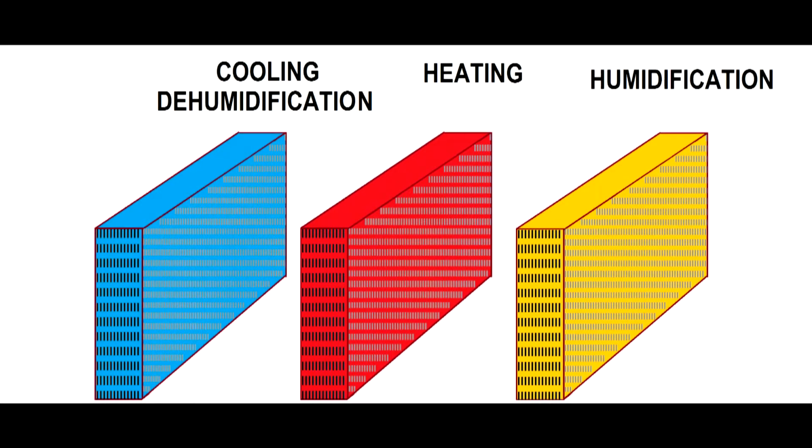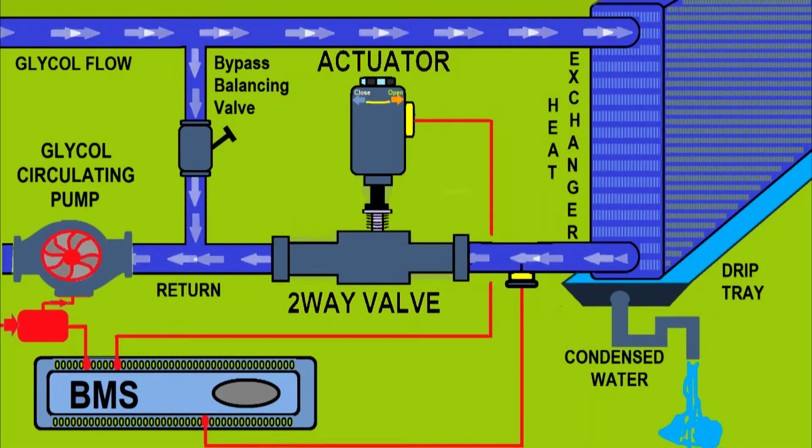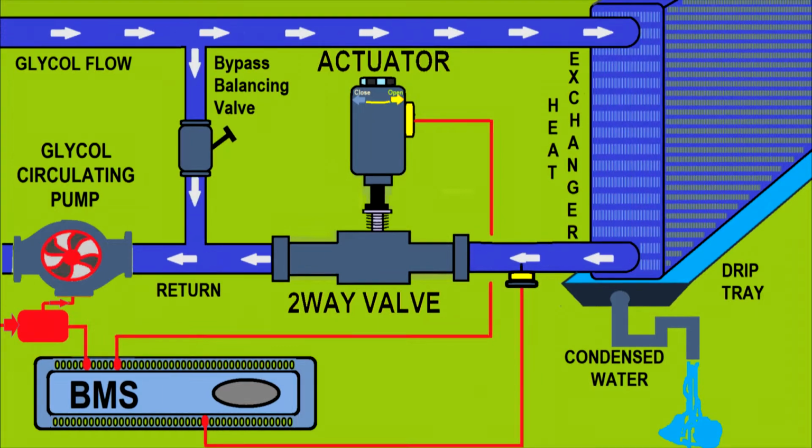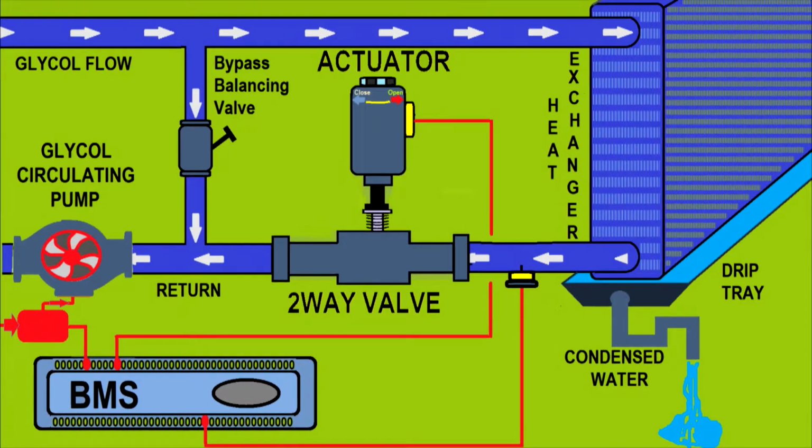Now I just want to show you how these heat exchangers work and how the actuators control the heating or the cooling agent which passes through these heat exchangers. This design is slightly questionable. As you'll see, we have a pump which circulates the agent through the heat exchangers, or it could even be a boiler, like a heating boiler. If this circuit is very short, it's pointless to have an actuator to close the access of the intermediary cooling or heating agent to the heat exchanger, because we'll have cooling inertia and the chillers could be disturbed, and if you have a heater, the boiler can be disturbed.